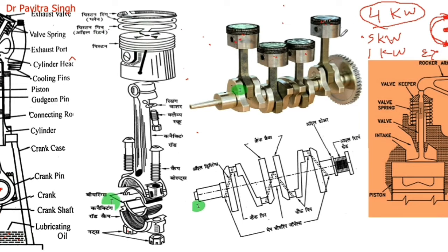So this is the arrangement of 4 cylinders in 4-cylinder engines. This is actually the crank, this one, like this. In the figure you can see this part. Here the oiling drills are there, means holes are there to lubricate these parts. So actually bearings will be here, here, here, here, here and here.